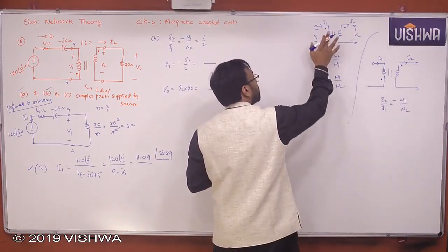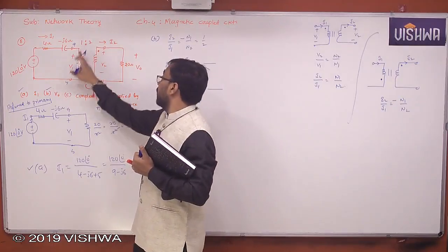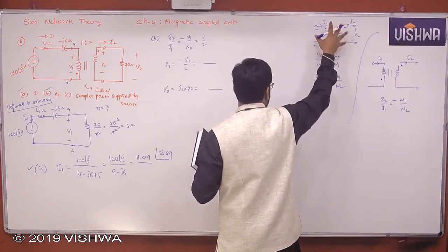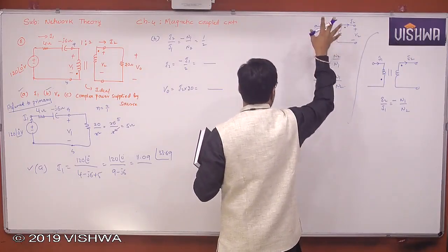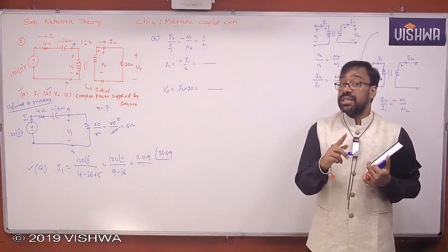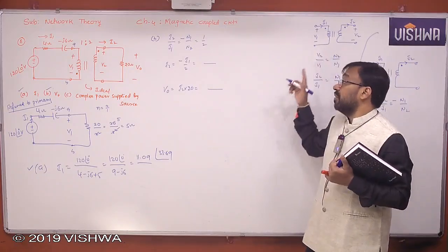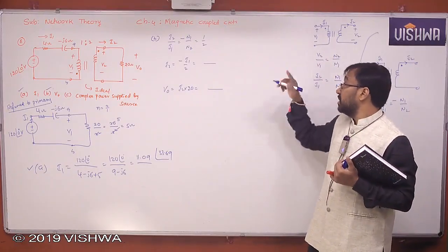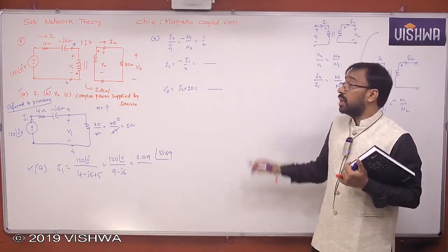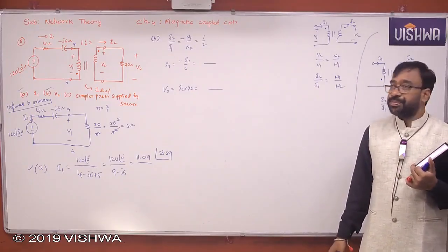Always compare with respect to this, whether the given transformer, current and voltage are the same as this or not. You take this as a benchmark example, and based on this you analyze whether the minus sign will come or not. I'm telling you, it's very sensitive. There are many chances of making a mistake. If you keep this in mind always, in the relationship of the voltages and currents in terms of the turn ratios, then you can easily solve the problems. That's it.